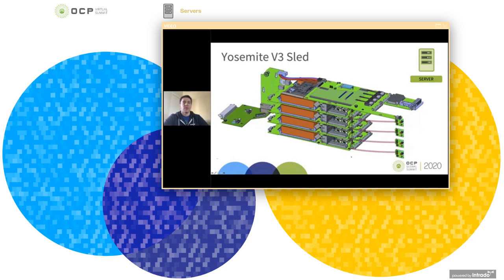Just to also call out that this is now a fully front-loaded server card. So it means you could take out a single server blade as a replaceable unit without taking the sled out of the power domain as well. We were also able to do a single server in Yosemite v2, but in that design, you would pull out the whole sled and the twin lake cards were vertically inserted. Now they're horizontally on a flat plane and can be removed on their own without taking the sled out of the rack.